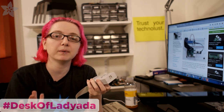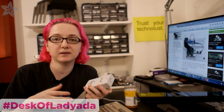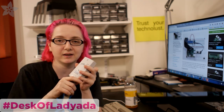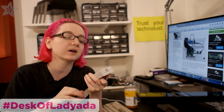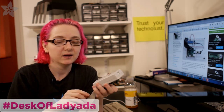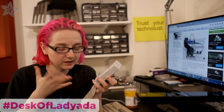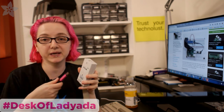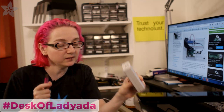So as new chips come out or they find bugs and improvements, you plug into the software and it'll update. In fact, pretty much every time I plug this in, it's constantly telling me there's a new firmware update for your J-Link to support more chips, because this is pretty much what everybody uses. So that's the J-Link, and you can get the educational version for $100. It's a good deal, but if you're doing commercial work like we are, at work I have a bunch of bases. We use the J-Link base, which is a little more expensive.